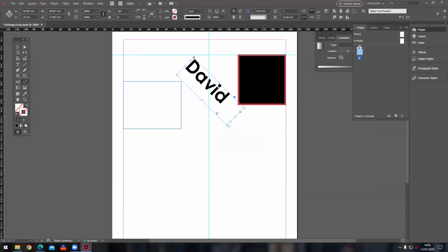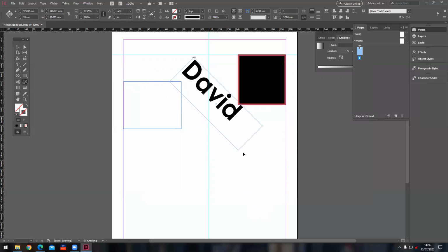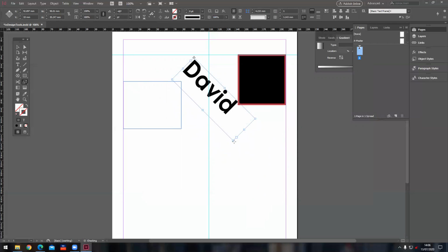Scale tool, again, it does what it says. You can make it larger. Now, you've got to watch the elements when making it larger. There's the width and the height and the percentage. You've got to make sure that you keep it to the same percentage. I'm keeping my finger down on the shift key. You see, I'm just clicking and dragging up and down and making it smaller or larger. But what I could also do, if I leave that, that's 100%, what it started at.